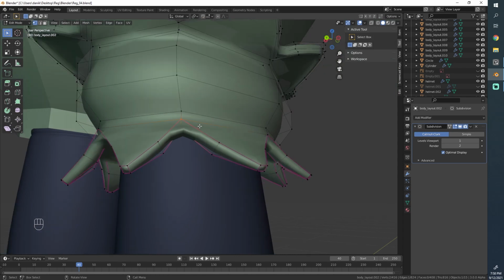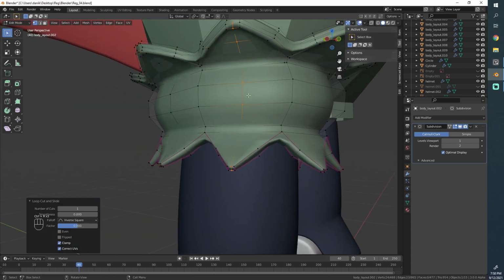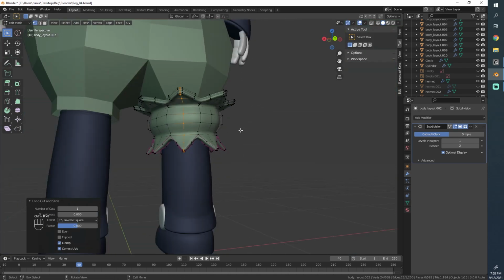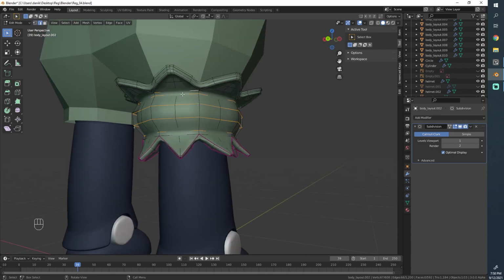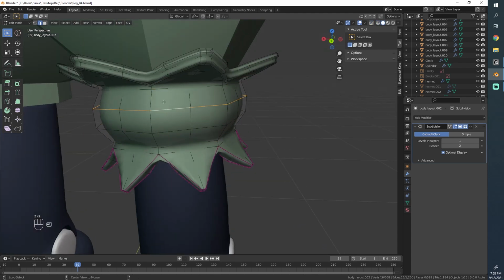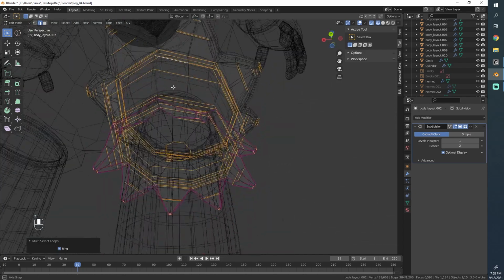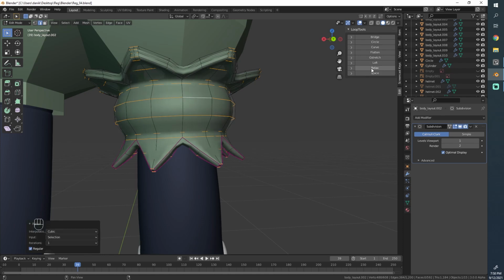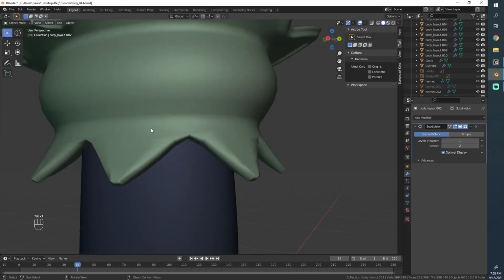Okay, we should have worked with a little bit more resolution on a second thought, so let's see if we can fix this still. I'm going to insert loop cuts right around this entire part, and then I'll try to select all these rings here. Maybe let's select one and go to select loops, rings. This will select everything all around, and let's see just what happens if we hit in our loop tools that we activated from the add-on. Let's hit relax, and that really improved things quite a lot. So that was a very smart move, I think.